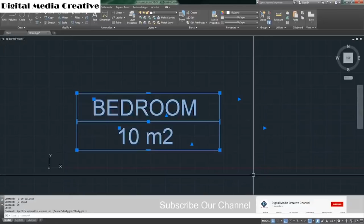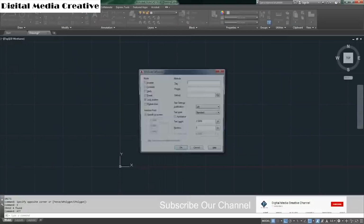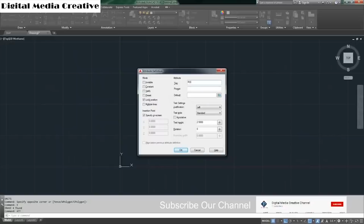So I'm going to make an attribute. You can type att for attribute. Then you can enter, and you will get a window. In the tag column you can make a room name, but make sure it is without space.